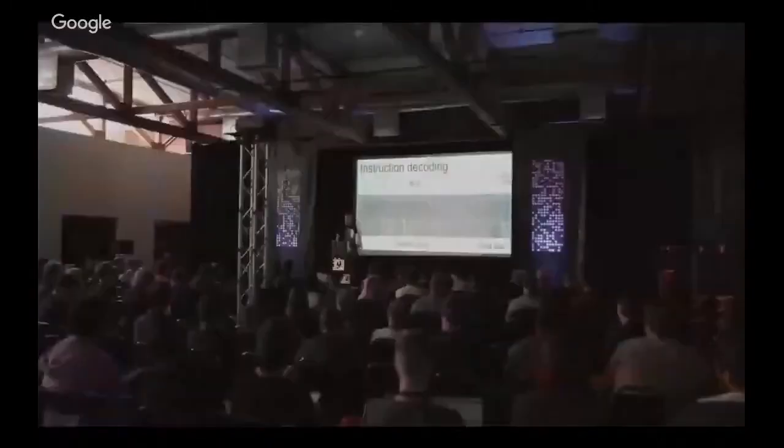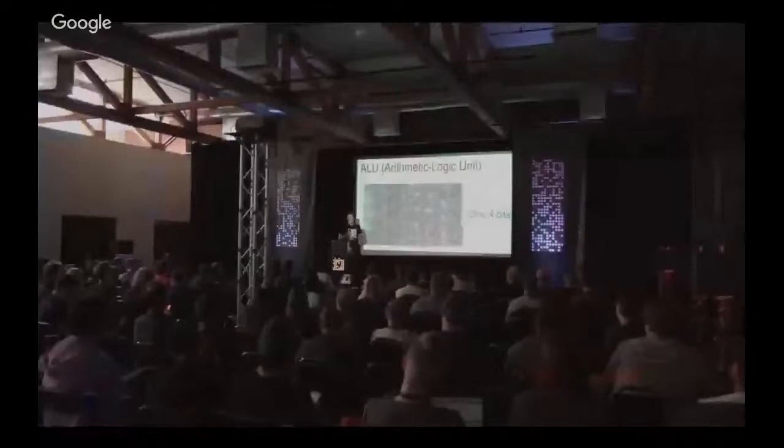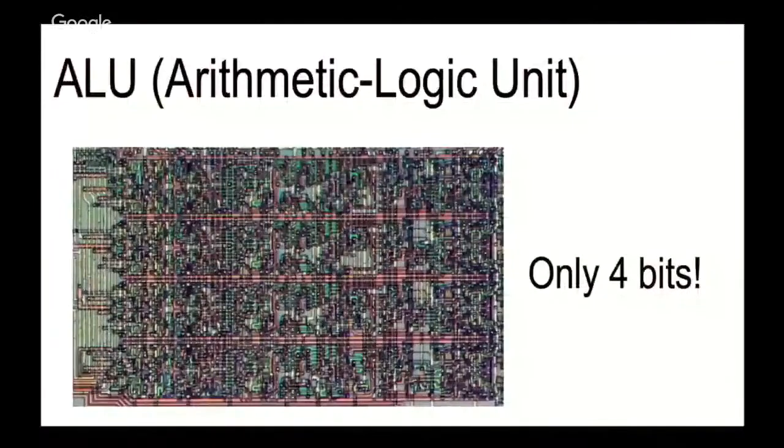The third interesting block is the ALU. This is where things actually happen in the chip, the addition, subtraction, bit operations. Most chips use a bit slice, so they'll have, for an 8-bit processor, 8 stacks of circuitry, one handling each bit of the data.